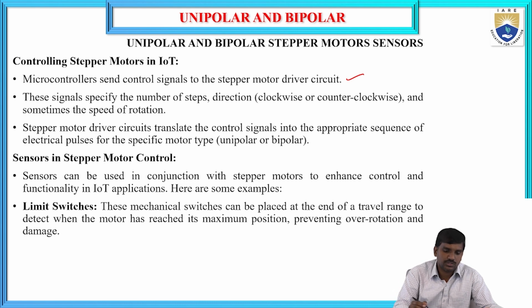Stepper motor driver circuits translate the control signals into the appropriate sequence of electrical pulses for the specific motor type, that is, unipolar and bipolar stepper motors.